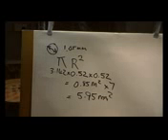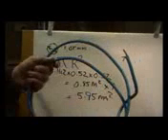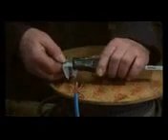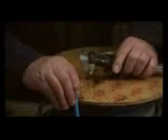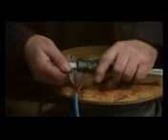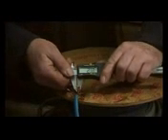Now I've just got another example. This cable here, it's somewhat fatter. So you need to be square on to this stuff, because if you're at an angle it will give you a seriously inaccurate reading.